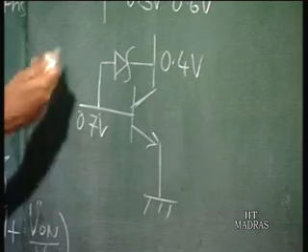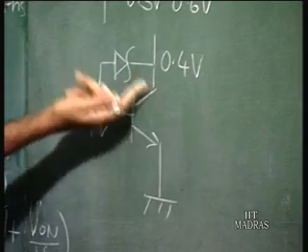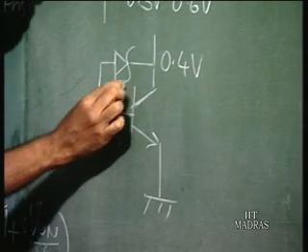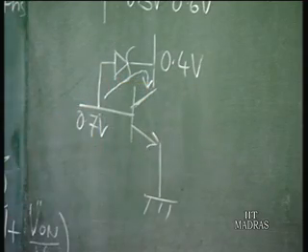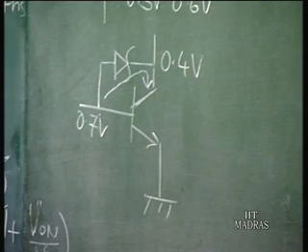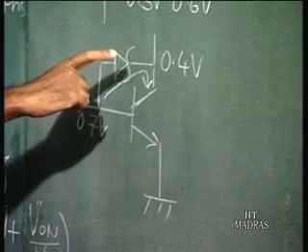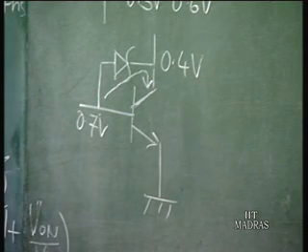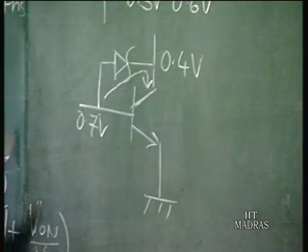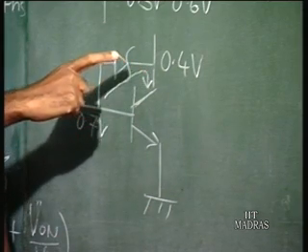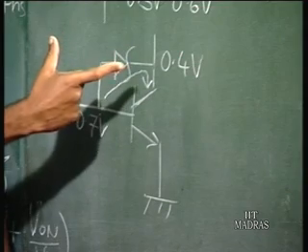this diode starts conducting, and then the excess base current, which was flowing into the base, will start flowing into the Schottky diode, and there is a conduction path from here to here. That is, it flows through the Schottky diode into the collector. In a diode, once it starts conducting, it is a very steep characteristic. The voltage is almost clamped to that value. So, this is almost clamped at 0.3 volts, maximum 0.4 volts.